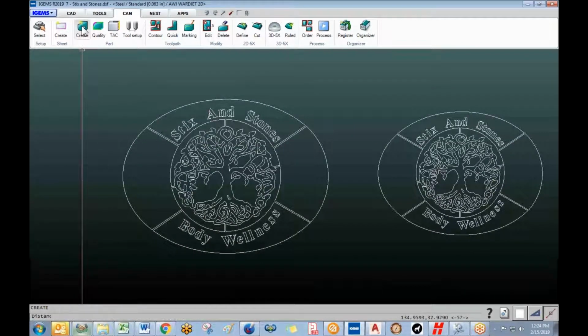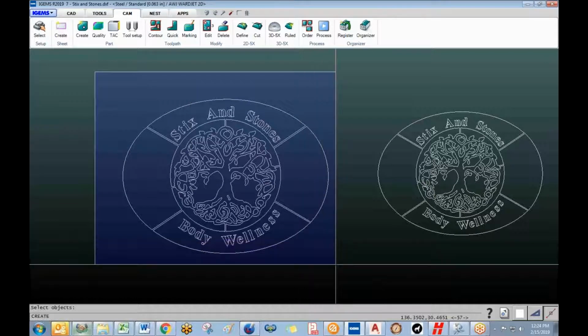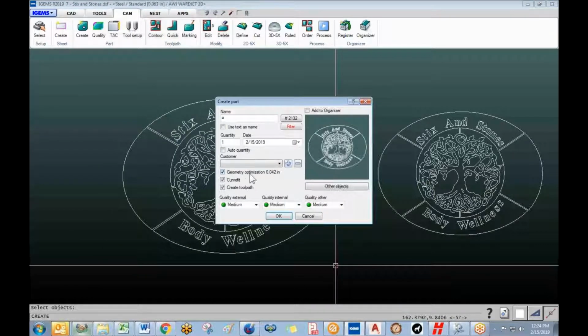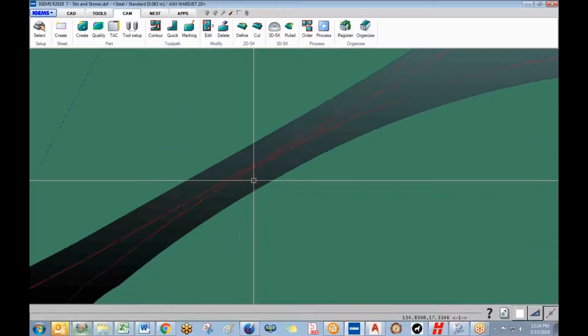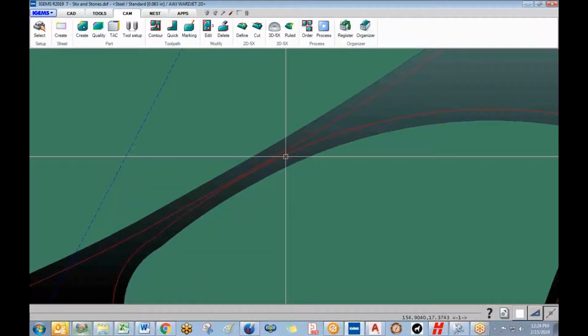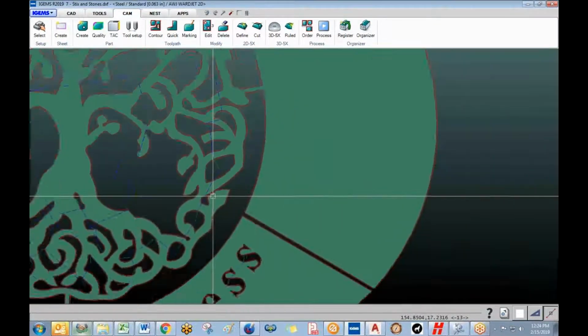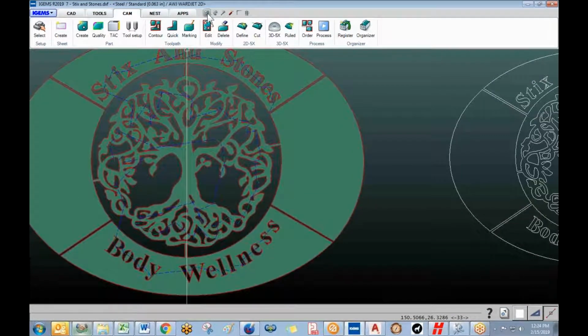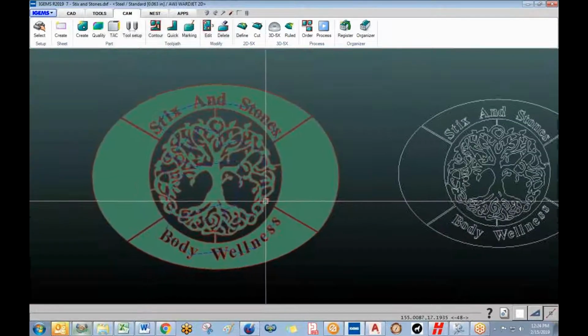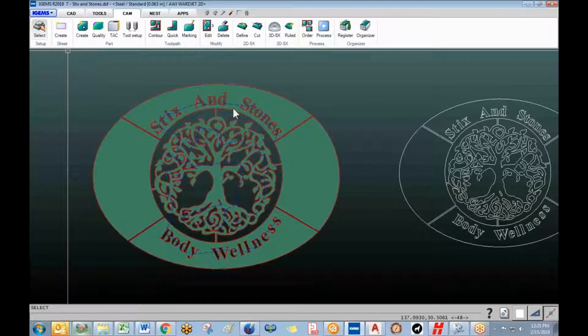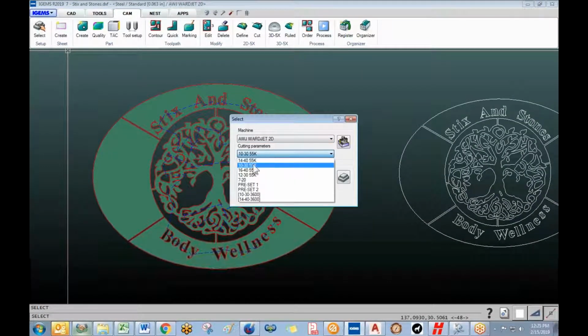First thing is, when I go to create that part, I can turn off geometry optimization, and that basically tells IGEMS, I don't care if I cut into my part a little bit, just do it. And we can see here now it can get through there. Now, since I told it I'm using a 1030 nozzle combination, it actually wouldn't cut into that part there. It might be a very, very small amount. If I were to change to a 1040, or excuse me, 1440, yeah, 1440, that makes sense.